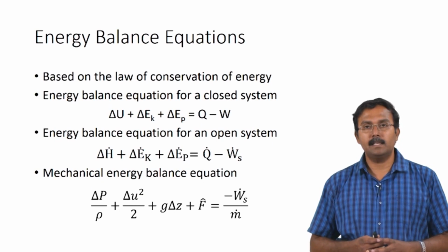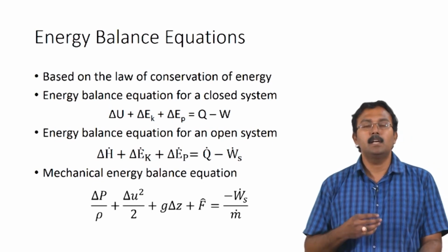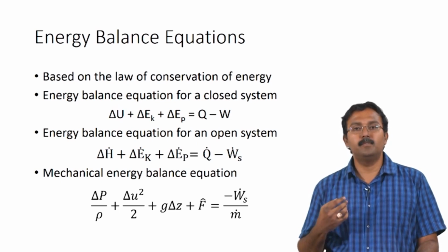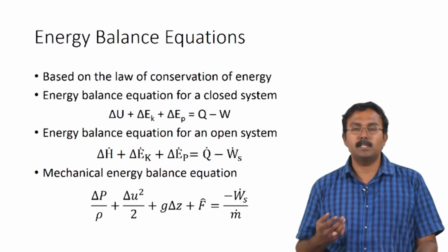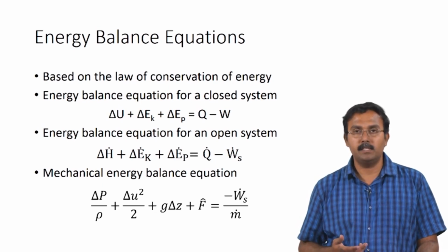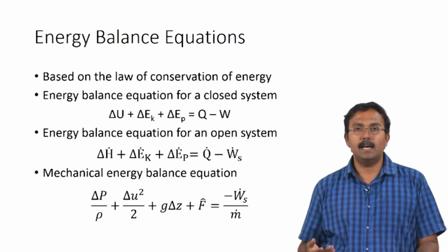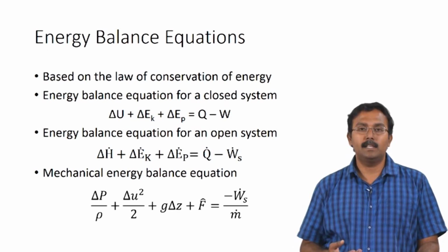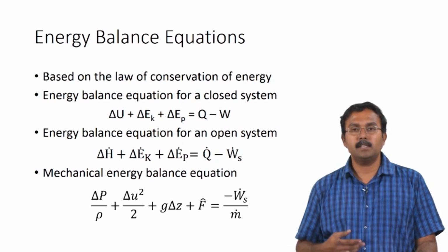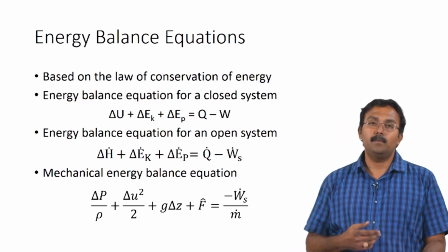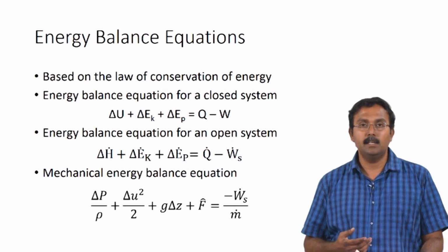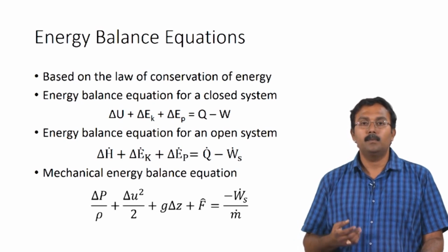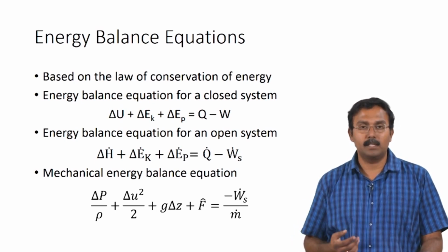When we perform energy balance calculations, we have to write appropriate balance equations. We have to identify balance equations which are based off of the law of conservation of energy. The law of conservation of energy states that energy can neither be created nor be destroyed. Based on that, we have developed different equations for closed systems, open systems, and we also have a mechanical energy balance equation where the chemical and thermodynamic effects are smaller, whereas the mechanical energies are more significant.